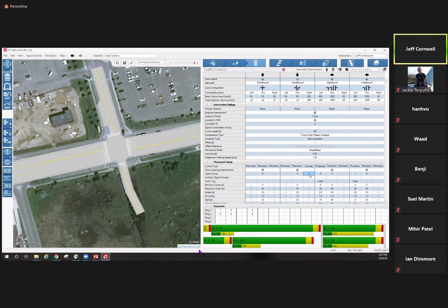I think for signal group here, you're going to want to put in what it overlaps with. So it's going to overlap with phase 5. So I think you want to put in a phase 5 there. So actually you want to put in both options. You can go with phase 4 or it can go with phase 5. So you click 4 and 5, make sure they're highlighted there, and click OK. And that is what an auxiliary signal group would be.